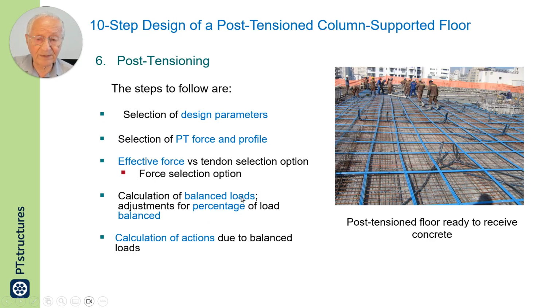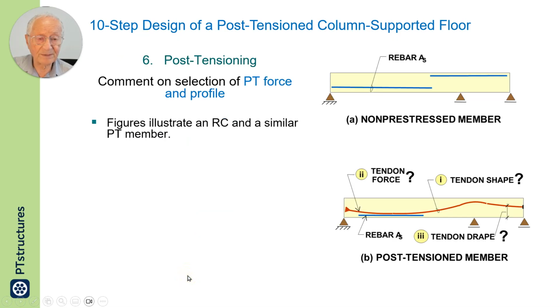In the load balancing method, you select the post-tensioning to provide uplift for a percentage of the other loads and go through the steps as I will describe in the following pages. Then we calculate the actions from post-tensioning due to balanced loads.